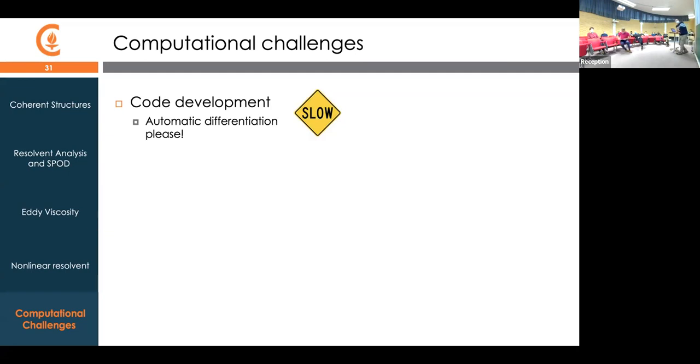Yes. If it's just Navier-Stokes, why do you need automatic differentiation, and why should it be difficult since Navier-Stokes is merely quadratic? Well, is that Lorette? Yes. Hi, Lorette. Hi. It's essentially the whole CFD algorithm that we're linearizing, not just the continuous governing equations. Does that make sense? No, but perhaps I'll ask you later. It's a code. It's not the equations. It's the code that we're linearizing.